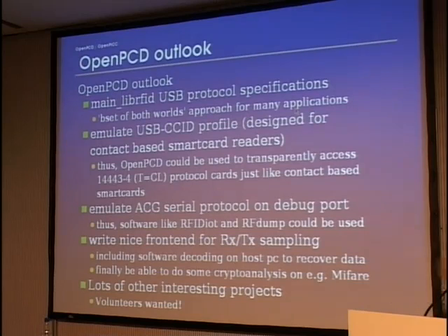So whenever you write an application, you write specifically for a certain reader. And software such as RFIDIOt, the RFID IO toolkit, and RFDump could be used because they support the ACG readers, which have a specific serial protocol, and if we emulate that protocol, then it could also work with the OpenPCD. So it's just a matter of re-implementing that serial protocol.